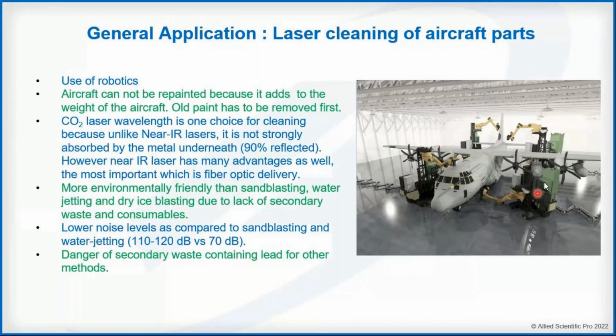So that's the reason you need to remove the old paint before putting on a new fresh layer of paint. Using lasers is a very good way of doing that. And if you use a near IR laser, you can adjust the parameters to make sure that it doesn't damage the substrate and cleans very effectively.